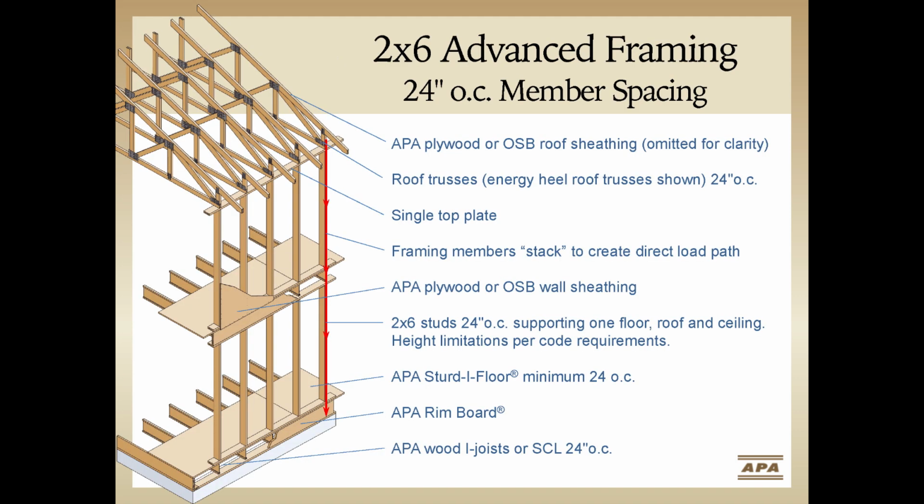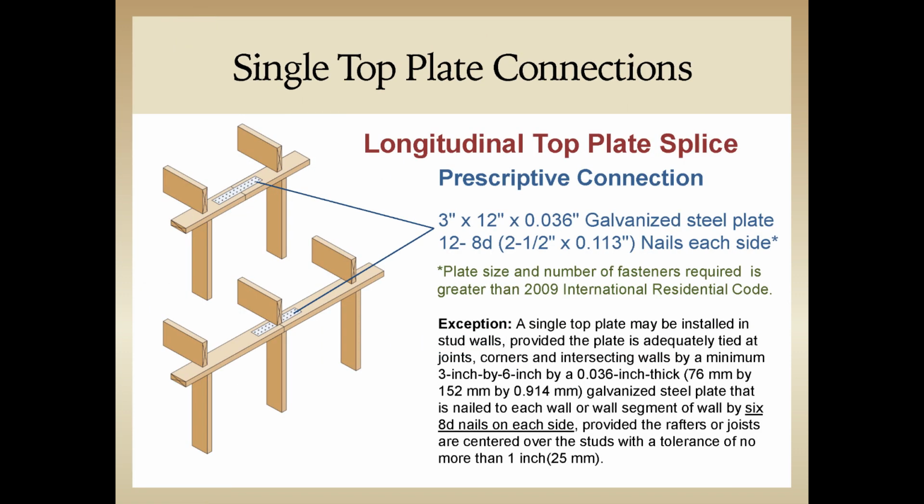One of the biggest challenges for framers is the move to stacked framing. So if we look back at this overall detail, we can see that everything is aligned at 24-inch stud spacing. Stacking your framing like this allows the option of going from a double top plate to a single. So let's take a look at what that's like. When a single top plate is used, which does require inline framing as we've discussed, the IRC calls for a metal top plate splice as shown whenever there is a splice.